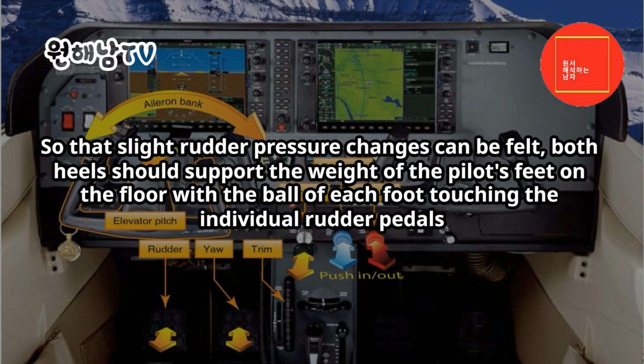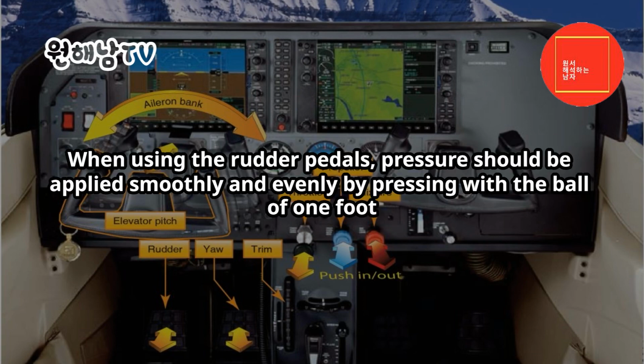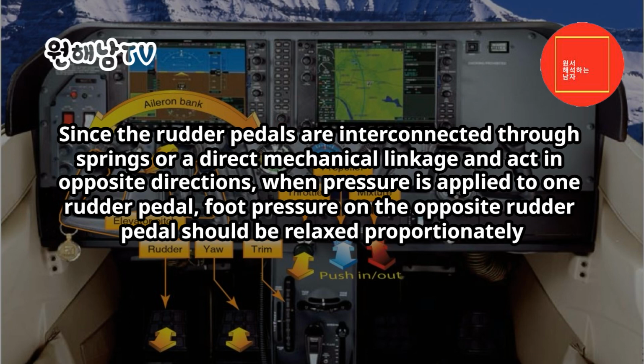So that slight rudder pressure changes can be felt, both heels should support the weight of the pilot's feet on the floor, with the ball of each foot touching the individual rudder pedals. The legs and feet should be relaxed. When using the rudder pedals, pressure should be applied smoothly and evenly by pressing with the ball of one foot. Since the rudder pedals are interconnected through springs, or a direct mechanical linkage, and act in opposite directions, when pressure is applied to one rudder pedal, foot pressure on the opposite rudder pedal should be relaxed proportionately.